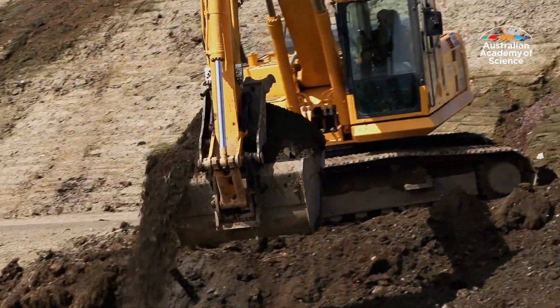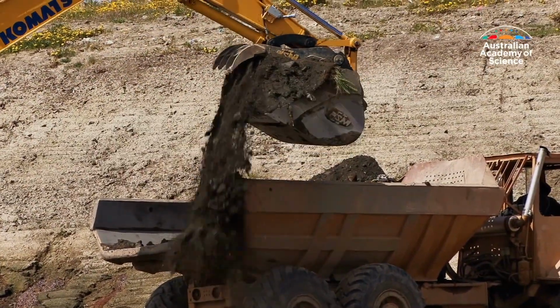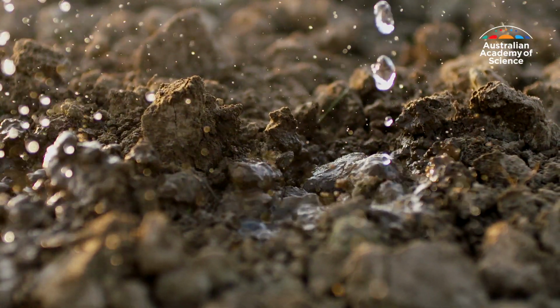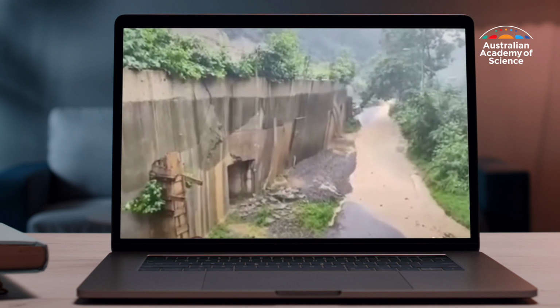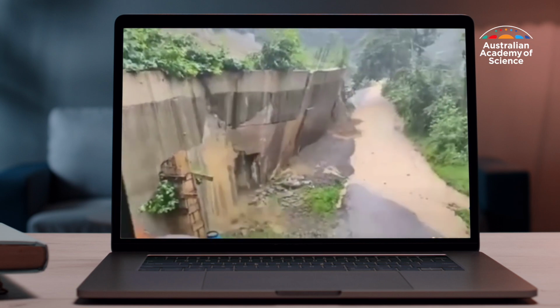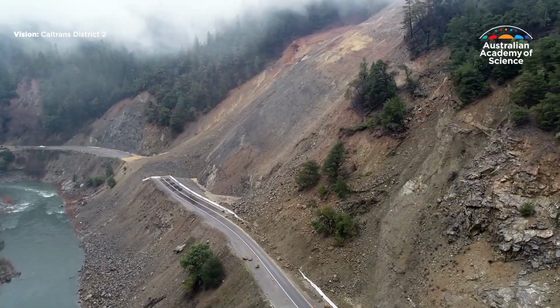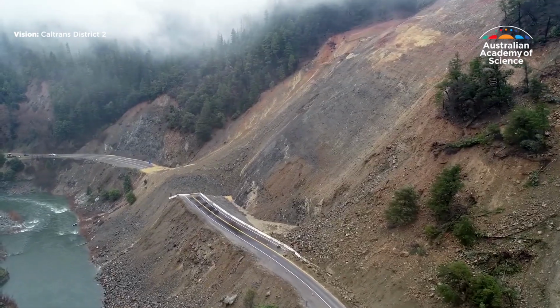Soil above groundwater surface is partially saturated with water, while its other pores are filled with air. But when unsaturated soil comes in contact with water during so-called wetting events, such as rainfall or a pipe leak, the consequences can be dire. Unsaturated soil can generate large deformation and even sudden strength loss during the wetting. That could damage infrastructure like slopes, foundations and dams, and even trigger landslides.